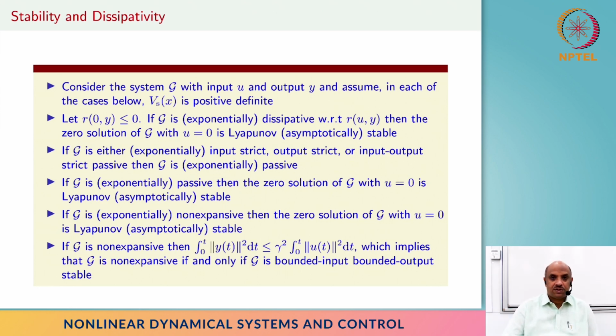The original definitions of stability in the classical control case started with this bounded input, bounded output stability, right? Though Lyapunov stability was already discovered, it was still not very well known. People used the notion of bounded input, bounded output stability for linear systems, and then eventually expanded the definition to nonlinearity. And Willems subsumes that notion through this concept of dissipativity, with non-expansivity as a special case, right? So in that sense, these special cases of passivity and non-expansivity are quite important.